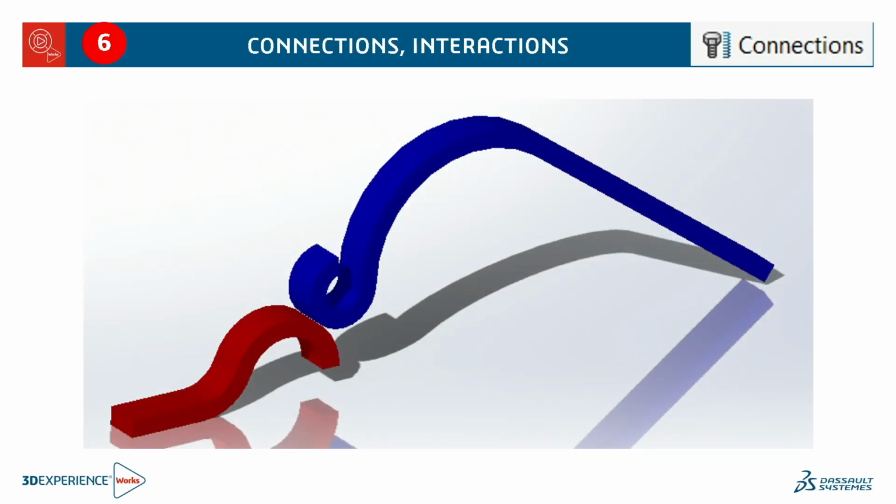Pairwise contact is also available in 3D Experience. It's been a standard approach for a long time now. But one of the things where typically it becomes trickier to start defining is when we consider large relative motions as part of our analysis. So if I go back here now to this clip, and we take that red part, if it's only moving a little bit, we just need that surface. But if I keep on pushing that red part inside the clip, then we're going to need to develop contact on the fillet surface and maybe even on the flat surface as well.